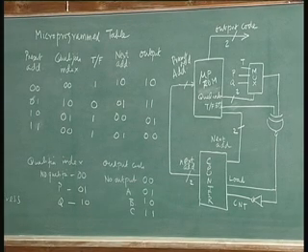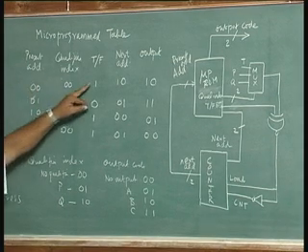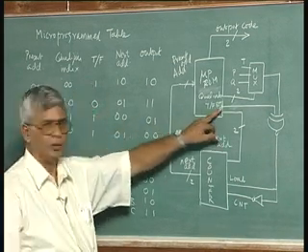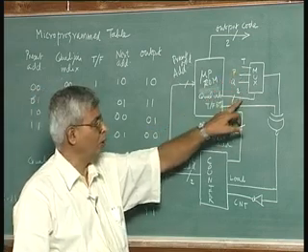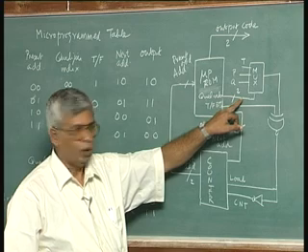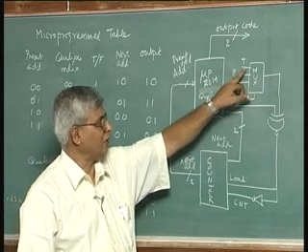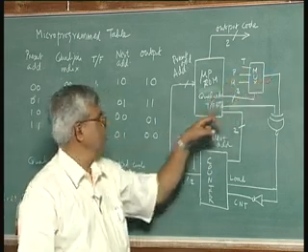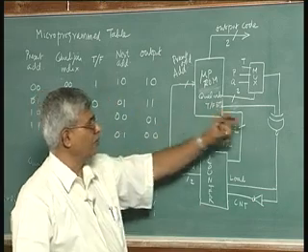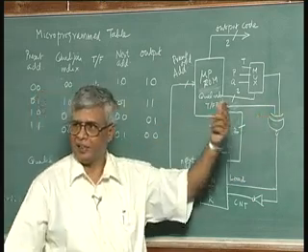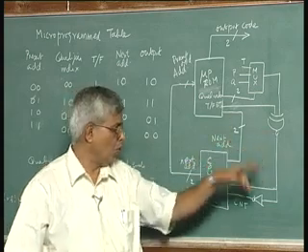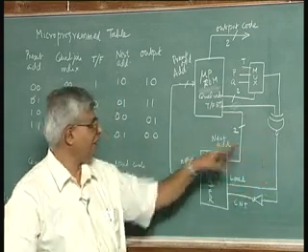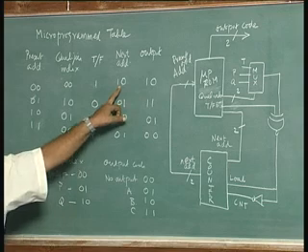For example, take the first row, no qualifier, true false bit is 1. No qualifier, this is 1. So, no qualifier index is 0 0. So, when 0 0 index is presented here, this is 1. So, 1 comes here, true false bit is 1 from the table. So, 1 and 1 compared, output is a 1, then exclusive NOR gate, not exclusive OR gate. So, 1 will load the next address, which is this.